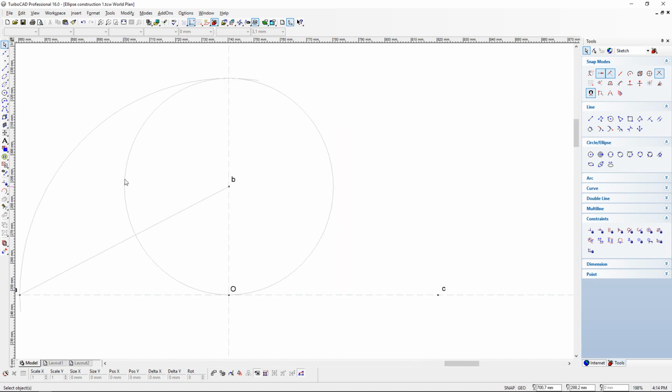Okay, so I want to also do the same with this circle here. I'm going to go back to the split entity tool, select it, click on the circle once that I want to work with, and then again I'm going to cut off a part of that circle just past the y-axis on that side, and then also just past this diagonal line here, because we want to just show this part of the arc, and I'll explain why we do that just now.